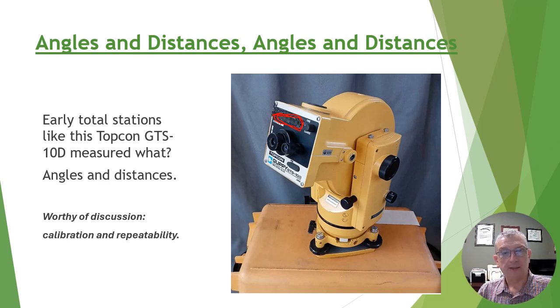You get your first distance, and if you were measuring to an iron pin, you would have it in the fine mode, and it would measure to the 100th of a foot. And you'd let it read about 3 times to get a little bit of an average, because sometimes it might bounce around. The technology was early. And if you're just locating the edge of a road, a tree, a house corner, well, you'd flip it into coarse mode. It would measure to the nearest 200ths, and it would measure about twice as fast.